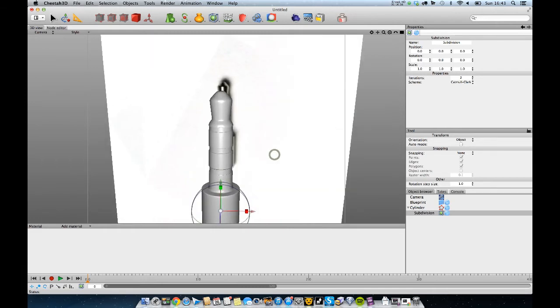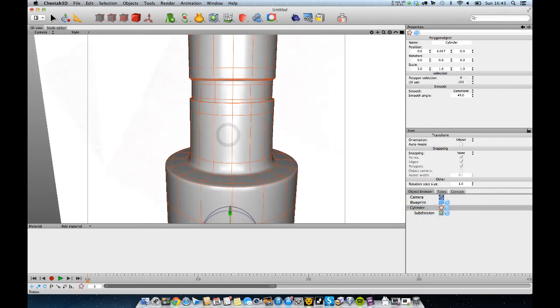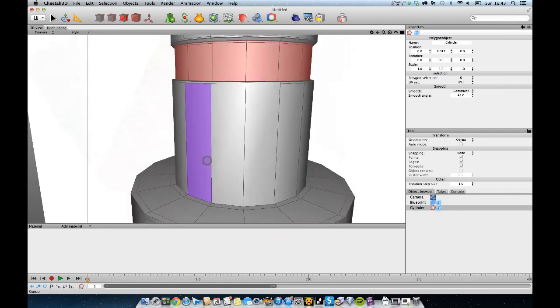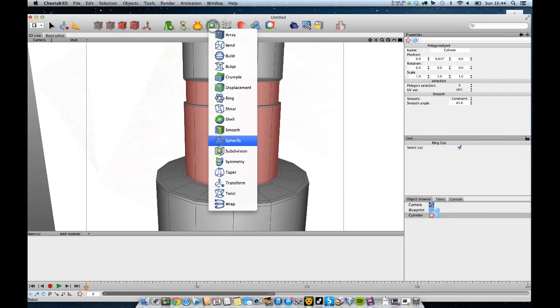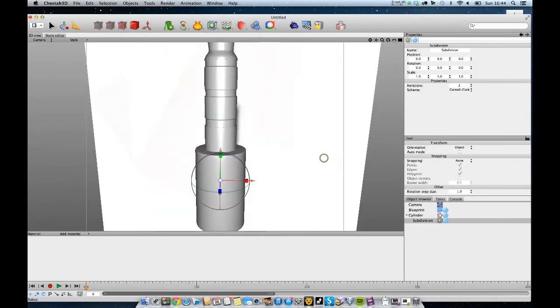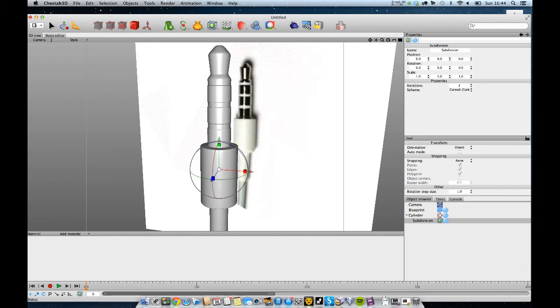Okay, so I'm kind of mostly alright. Again, just the smoothness down here I'm not mad keen on. What I might do is just drop a bevel on that. I'm going to delete the subdivision. I find it gets in the way quite a lot. Yeah, what I needed to do there was just add a ring cut, just about there. That should be fine. Throw that subdivision on again. That's it. That's much better. Right, we're going to go with it this time. Happy now.